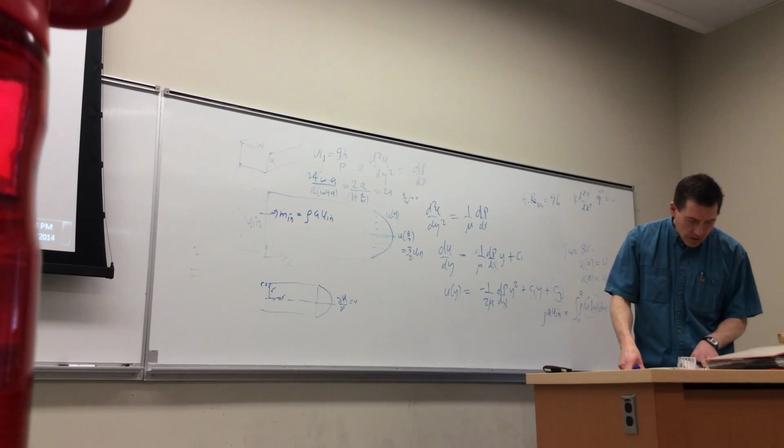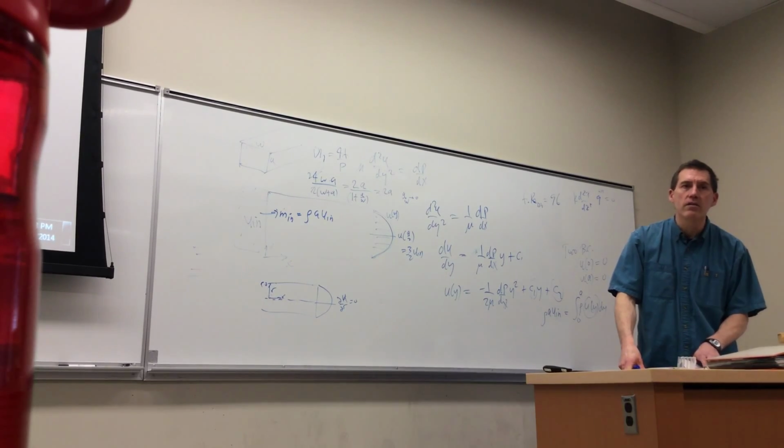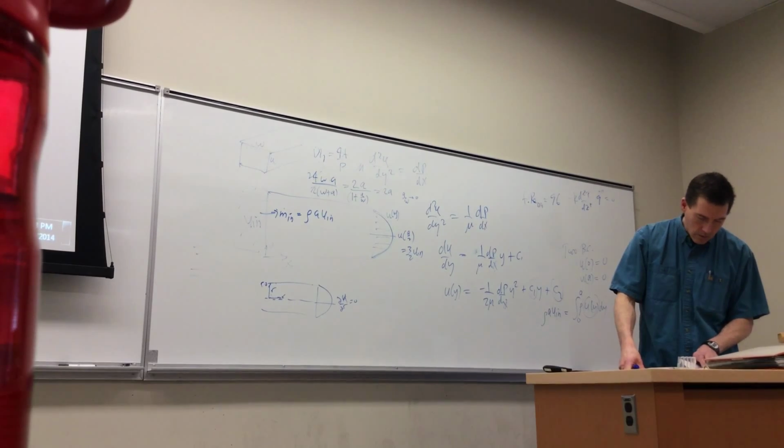Yeah, and that's what C asked you. The friction factor is estimated from the expression F equals C over Reynolds. C depends on the flow cross section. What is the C for parallel plate channel? It's 96. Or should be.